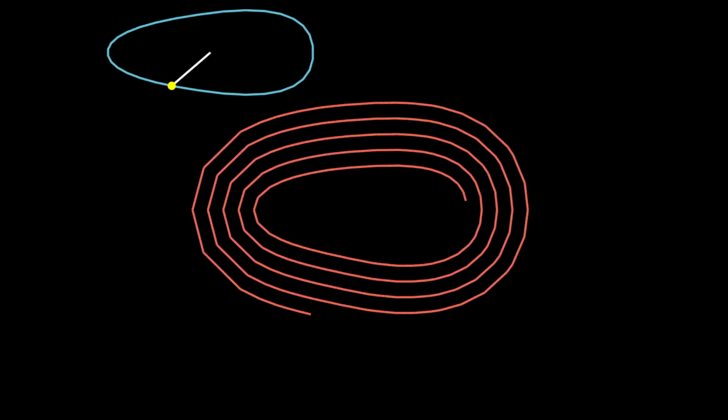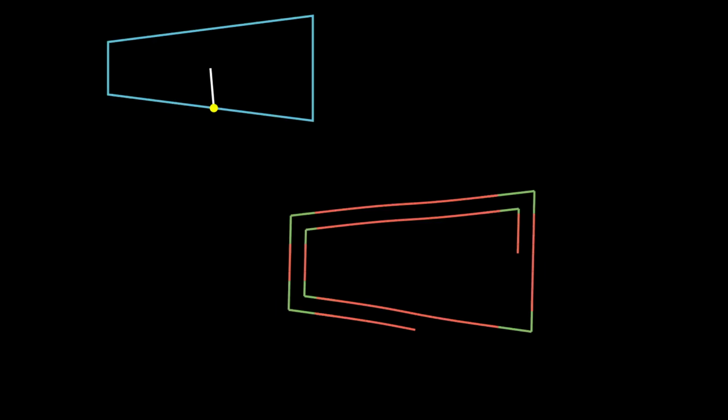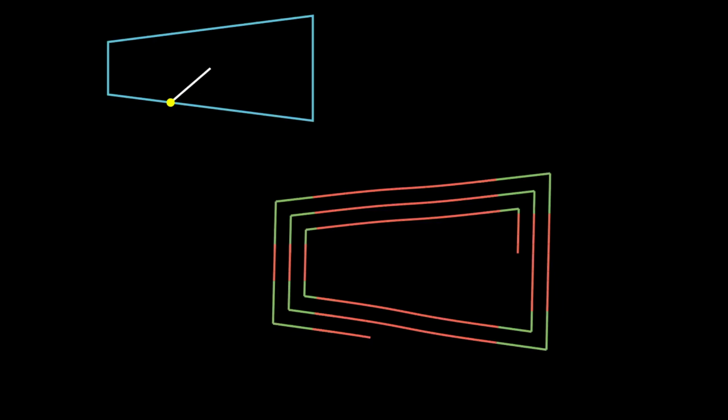An alternative way to fix the corner cutter problem is to detect when we switch to a new line segment and create an intermediate point where the corner should be. We do this by calculating the intersection of the previously generated points with the next two generated points. This algorithm works really well, and we get a nice looking coil.